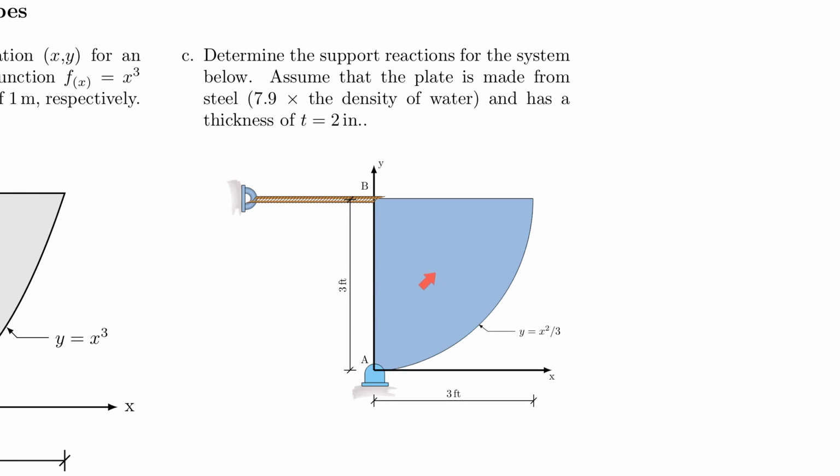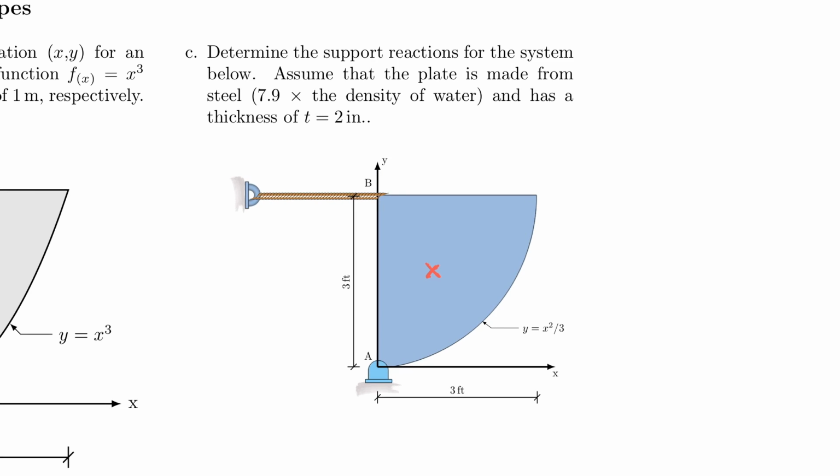And it wants to, of course, fall down under gravity. And how does it want to do that? There's actually what's called the centroid in a geometric sense, or the center of gravity in a physical sense. And I pretend for a second that's right here in the plate. That's obviously not correct, it's not to scale, but you probably will understand that gravity wants to take the entire weight of the plate and pull it down in that direction.